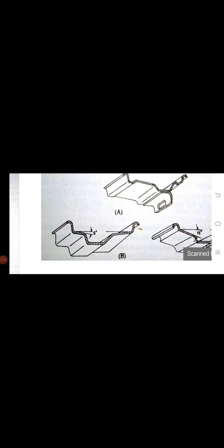And this one is the U-type drop center 15-degree taper ring. The sitting angle of the taper is about 15 degrees, and tubeless tires and large section tires with relatively flexible beads are used for vans, buses and medium sized trucks. These tires use a single piece wheel base rim having relatively shallow flanges at the edge of 15-degree taper bead seats. So the tire bead seats are a 15-degree taper.